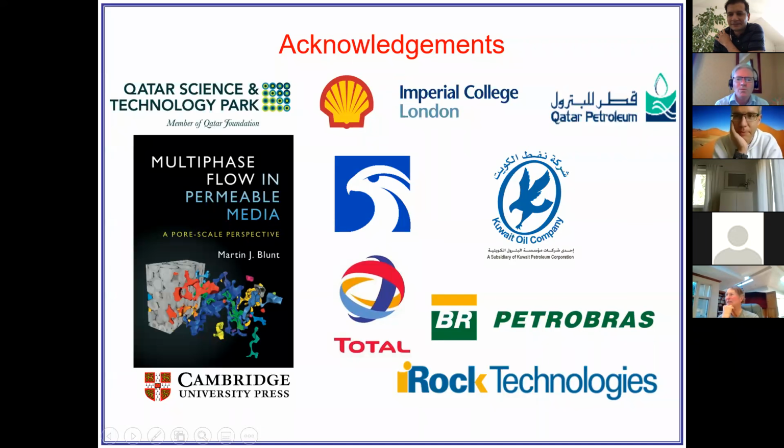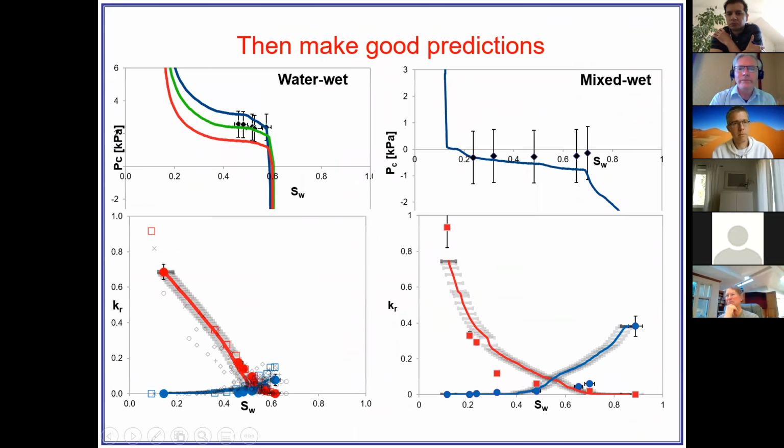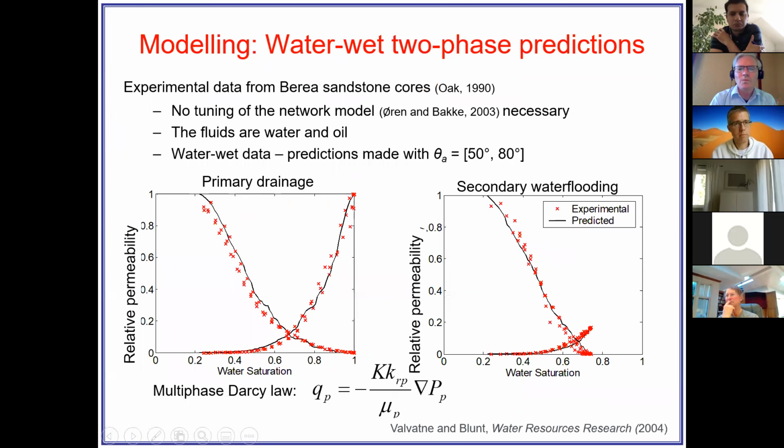So you explained very nicely how complex it is under dynamic conditions, and you mentioned the need for improving the theory. And it seems to me that the improvement you are currently providing is related to one parameter, which is the relative permeability, and a bit in the capillary pressure formula, capillary pressure saturation relationship. I didn't see that. But shouldn't really the improvement go beyond that, not just the parameter, but look at Darcy's law itself that offers a seemingly linear relationship between pressure gradient and flow rate, but then you show it's not really linear. And so shouldn't really one look at that as well?